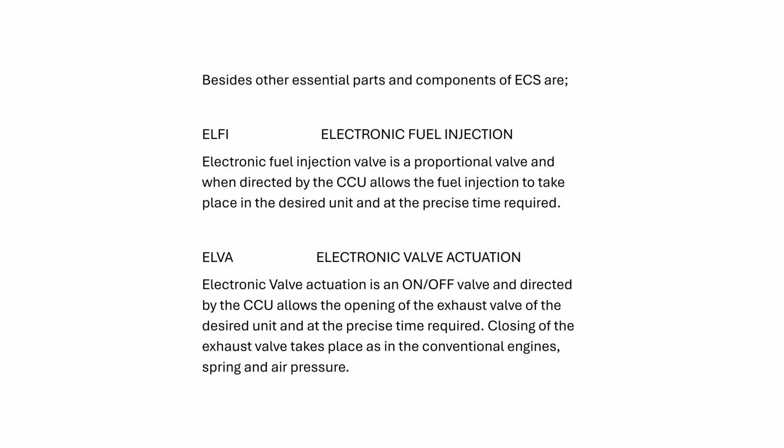ELVA was electronic valve actuation on the older engine. It may still be available on certain engines which you happen to go on board. The exhaust valve is on/off. It's only on/off because the exhaust valve needs to be open and closed. There's no midway open, halfway open, nothing.